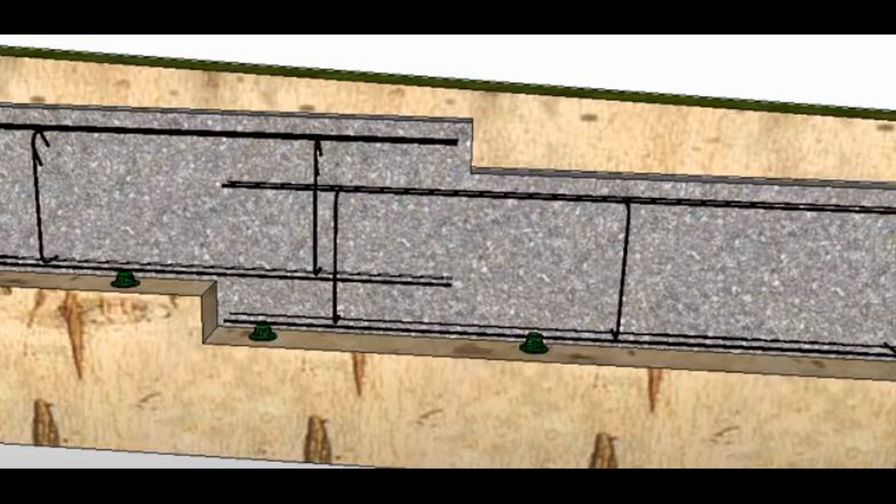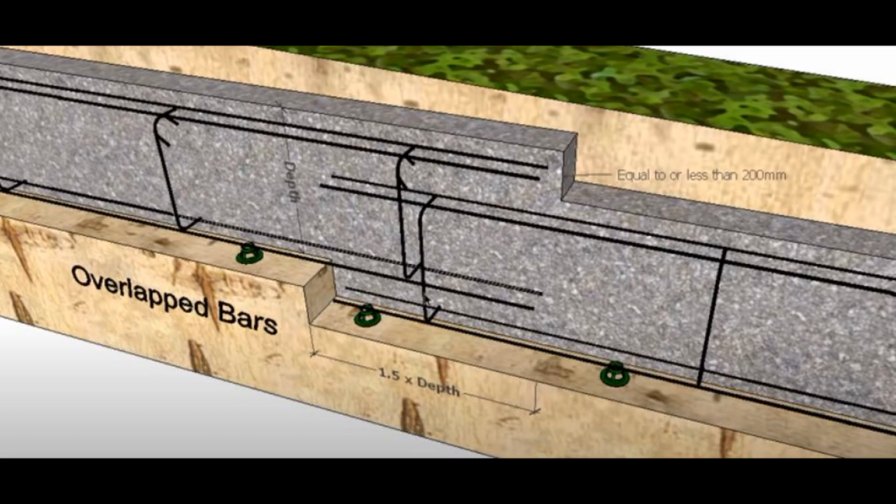For a gentle slope of the ground, which is less than 2%, steps in a footing construction need to be avoided. Ideally, the focus for the construction should be the design width and depth of the footing. It may be achieved by leveling the subgrade by digging extra.